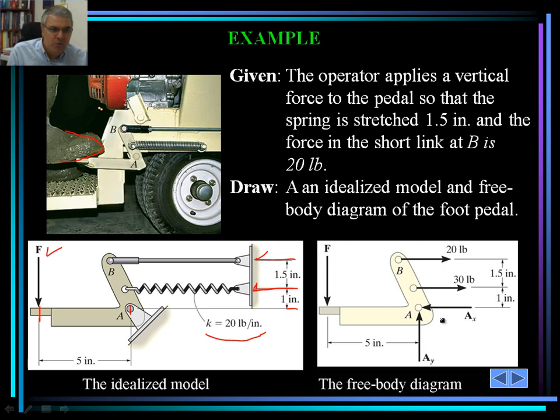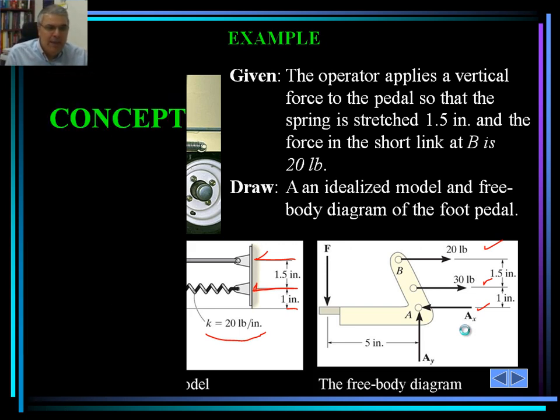And for point B, there would be a reaction which would translate into that 20-pound force. So it's very important to realize that at A there is a pin, and as a result we only have reactions in the x and y directions perpendicular to point A.